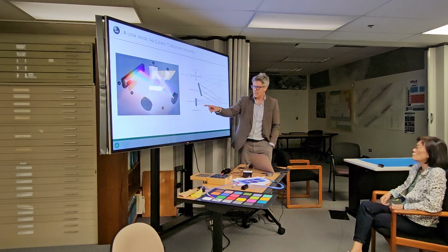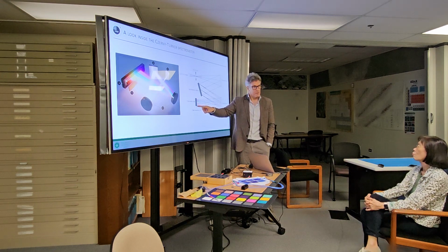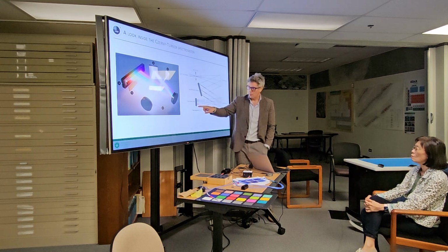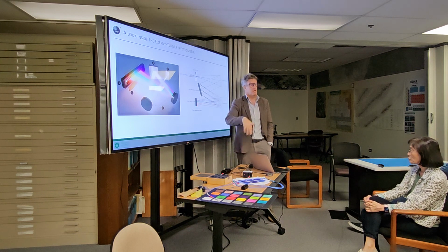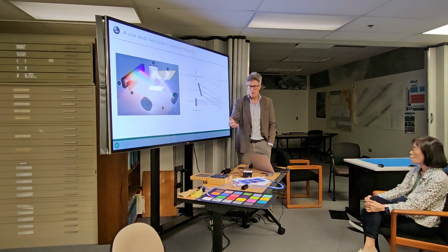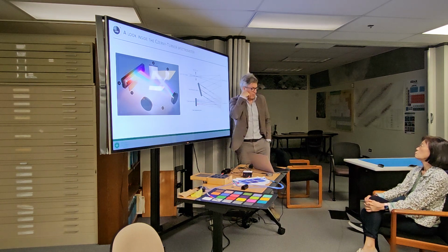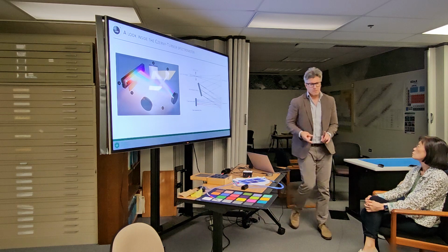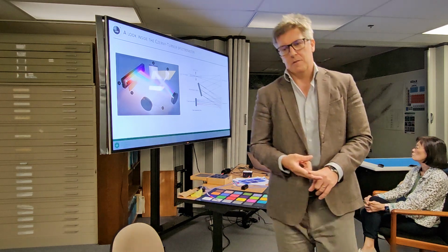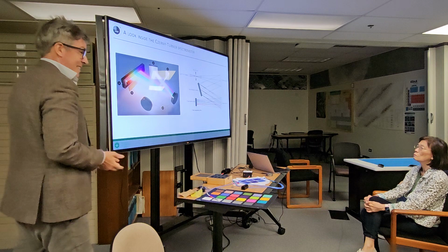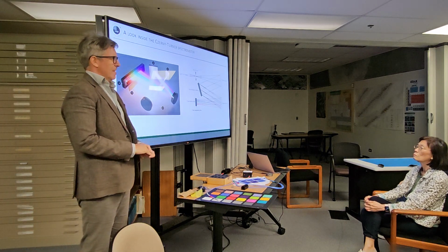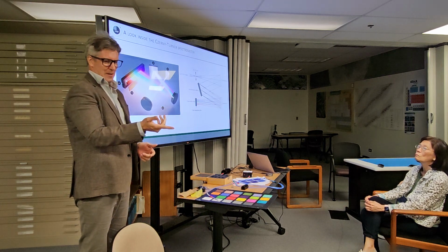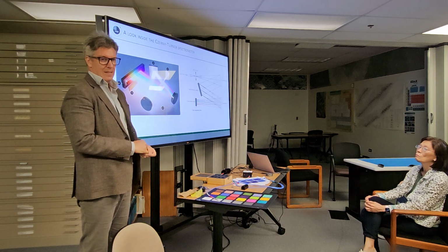So basically we're focusing light of one wavelength, or photons of one energy, onto one pixel in this focal plane array, and then another wavelength onto the next, and another wavelength onto the next. So that's what I'm talking about, spatial and spectral resolution. In this case, there are two types of focal plane arrays that are commonly used in reflectance spectroscopy. One you'll have heard of, a CCD array, charge coupled device. The other, which they use in phones, is a thing called a CMOS detector.